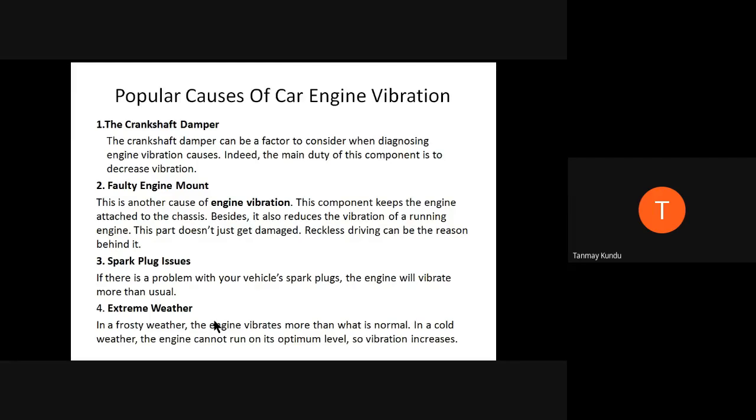Third, spark plug issue. If there is a problem with your vehicle's spark plug, obviously the engine will vibrate more than usual. So due to a faulty spark plug, a vibration problem may be generated. Next is extreme weather. In frosty weather, the engine vibrates more than what is normal. In cold weather, the engine cannot run at its optimal level, so vibration will increase. So this is the case for extreme weather conditions.